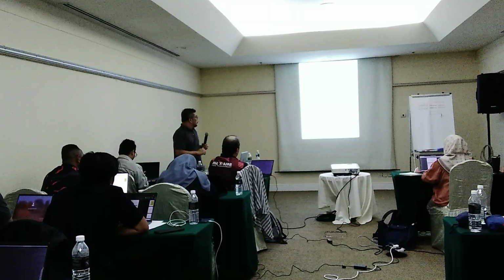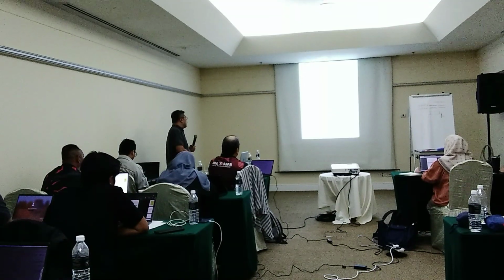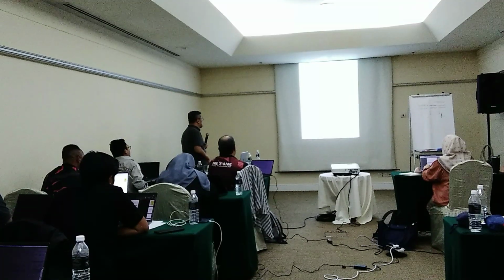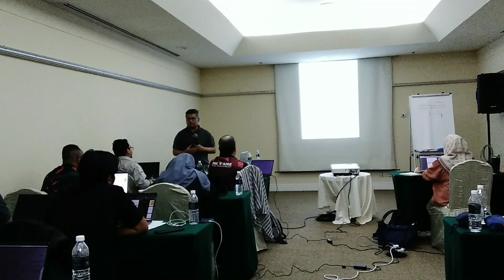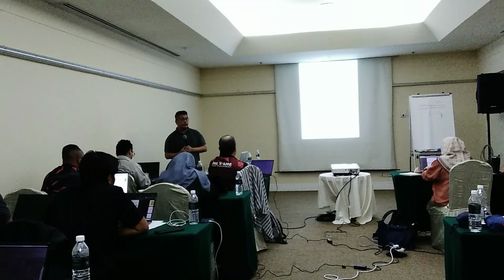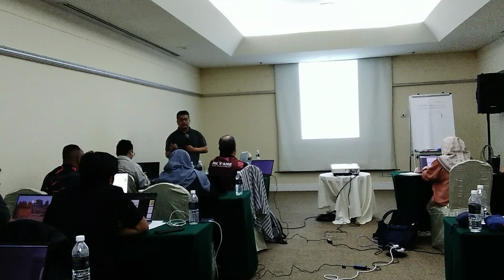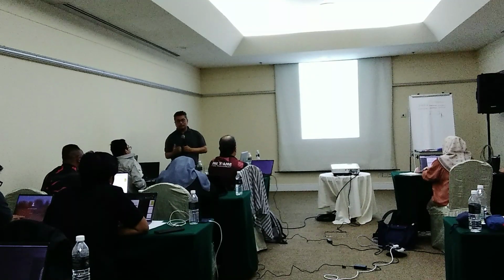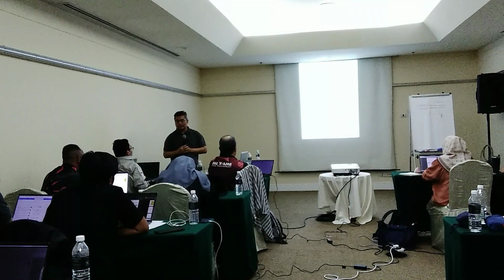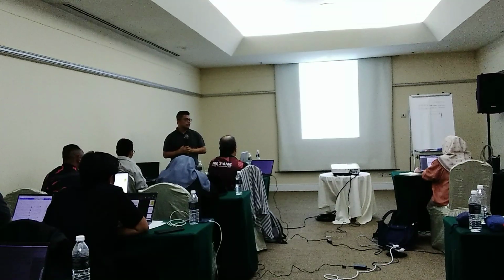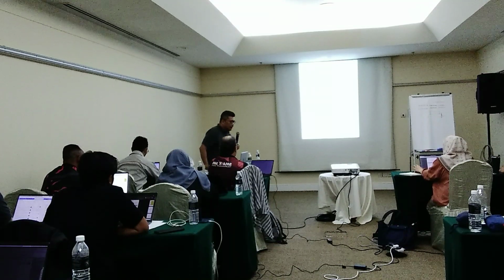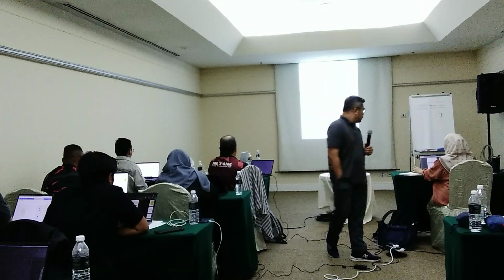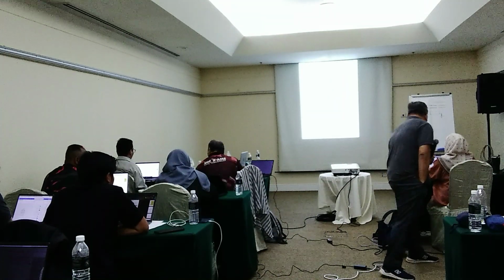And one more thing, any aspect scored 9 points automatically qualifies the input for further analysis and countermeasure, regardless of the RPN. Even if the RPN is 40, if severity is 10, you have to reduce the severity. Okay, any questions so far? Score 9 means RPN? Come again?